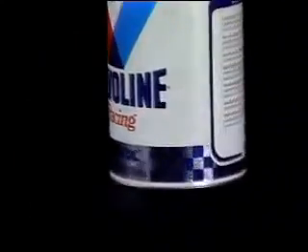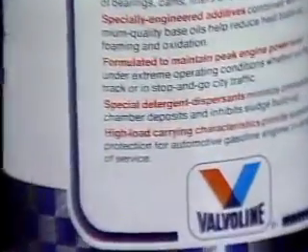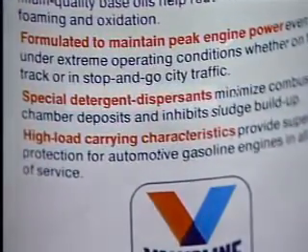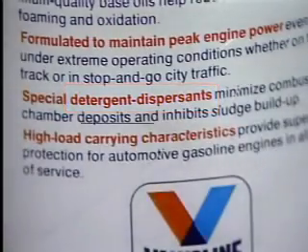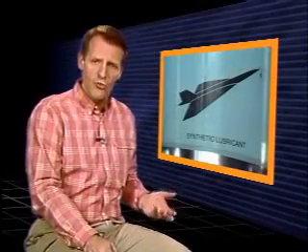And to reduce the formation of carbon deposits in sludge, chemical additives called detergents and dispersants are added to many oils and greases. These additives keep particles in the lubricant suspended so that deposits in sludge don't form. Additives are able to make natural lubricants suitable for many different applications. But there are some extreme conditions where even additives aren't enough.